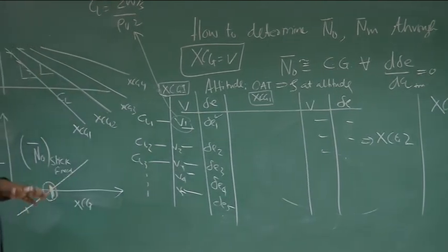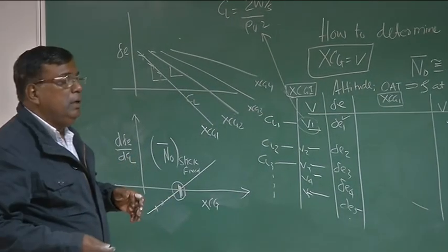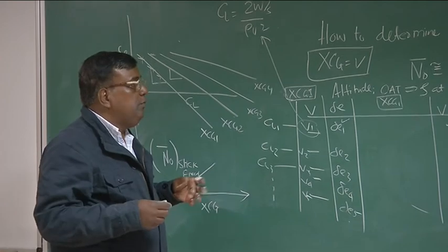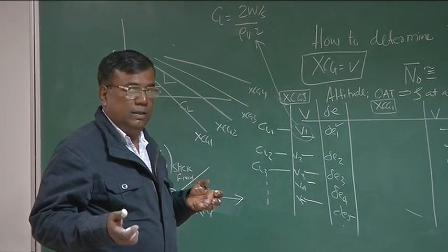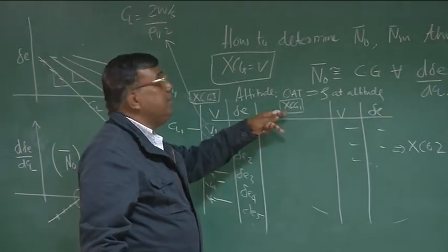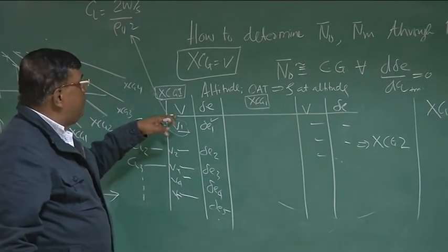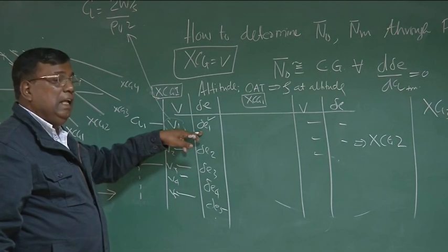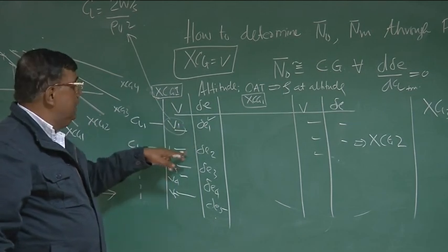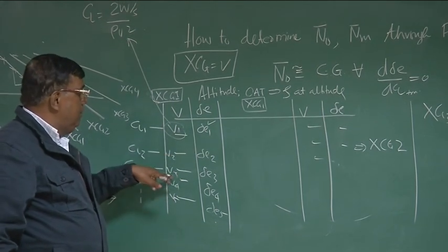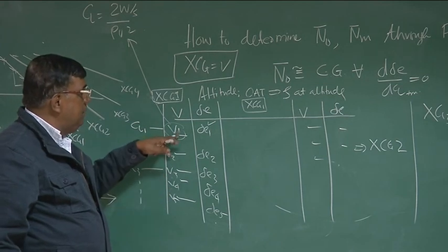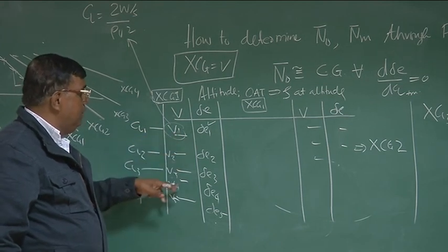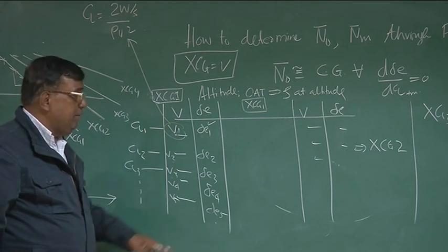Right? I fly in a configuration, let's say 4 people, and we have fuel in the tank, so we find out the xCg location for that configuration. I call it xCg1. Then I cruise at V and check what delta E elevator is required for trim. Similarly for V2, V3, V4, V5. So I have a series of V1 delta E1, V2 delta E2, like that, V5 delta E5.